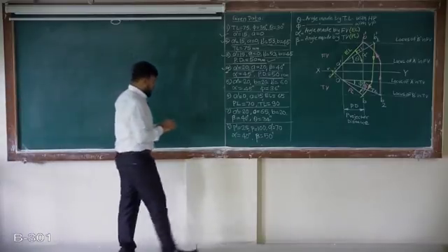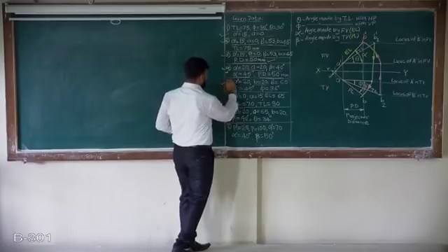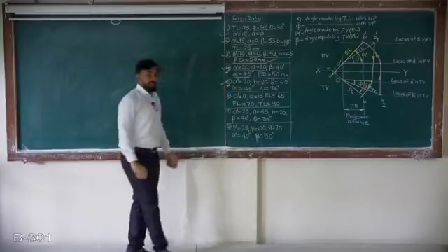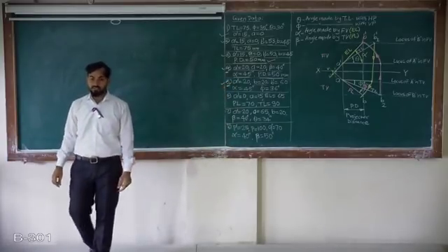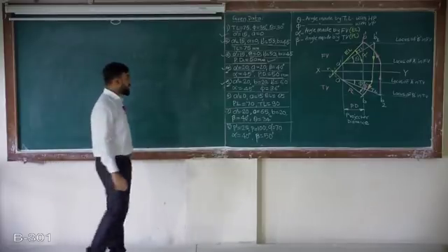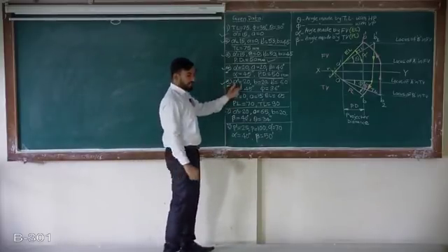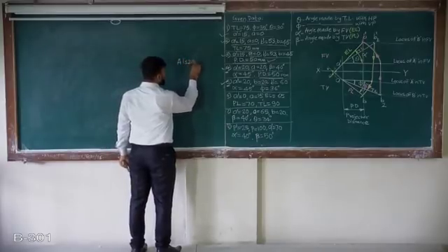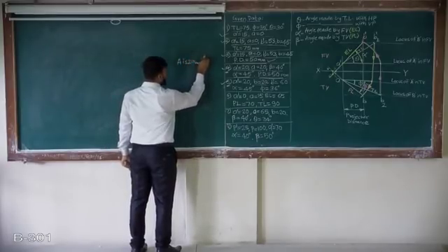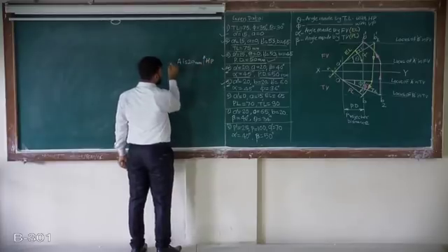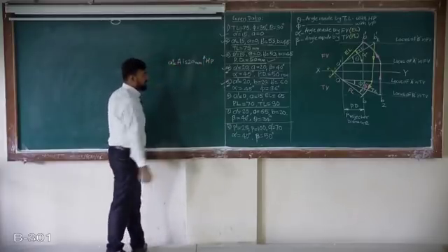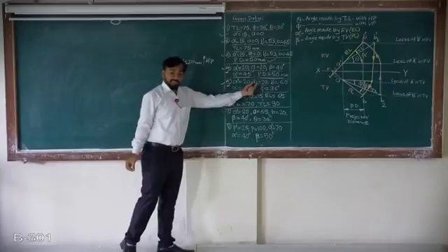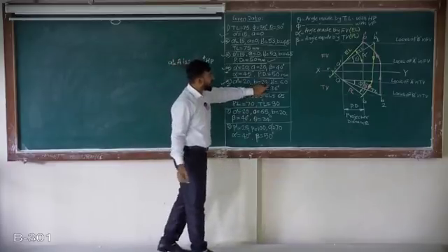Next is question number 5. So what is given in question number 5? Read it very carefully. It is given that point A, it is simply a point A, is 20 mm above HP. So above HP is given, so I can say this as A dash 20 mm. Next, very important, B is 20 and B dash is 16.